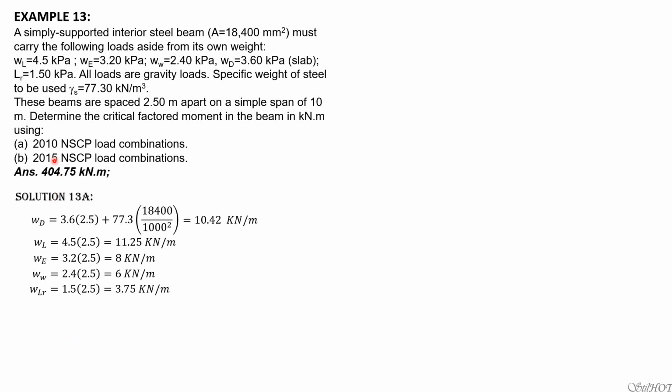So load combination 1 from 2010, that's the formula. This will not control because F is 0. This is due to fluids. It's 0, so 1.4 of dead load only, and definitely it will not control.